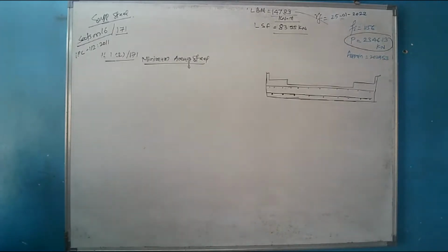अगर डक्टिलिटी फेल हो रहा है तो इसका मतलब इलोंगेट हो रहा है, यील्डिंग नेचर का फेलियर हो रहा है। यील्डिंग इज ए टाइम टेकिंग प्रोसेस, एकदम अचानक से यील्ड नहीं होता है, स्लोली यील्ड होता है स्टील। So you will have sufficient time to make the correction, that's why there is a limit to that. अगर मैंने नहीं प्रोवाइड किया मिनिमम एरिया तो क्या होगा? बोलता है ब्रिटल नेचर ऑफ फेलियर। ब्रिटल इज सडन फेलियर। अगर स्टील भी प्रोवाइड किया लेकिन बहुत कम प्रोवाइड किया, less than the minimum, it will get crack.